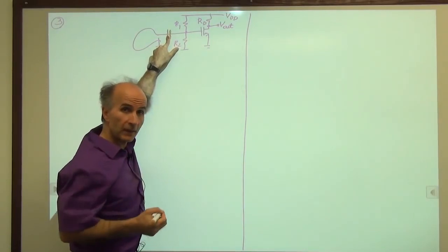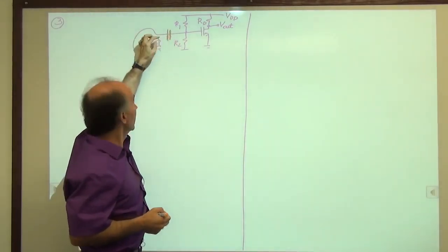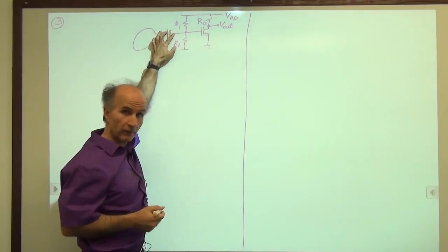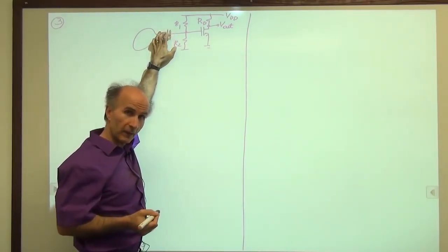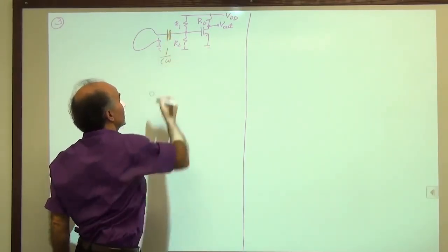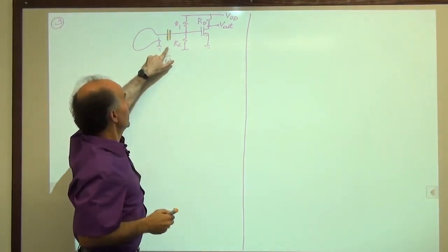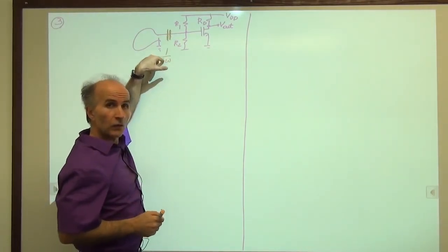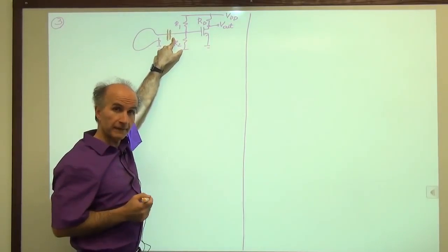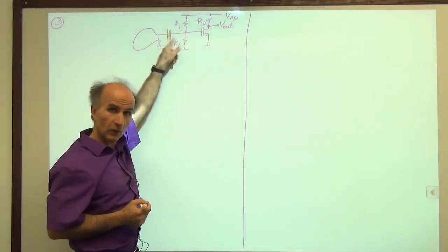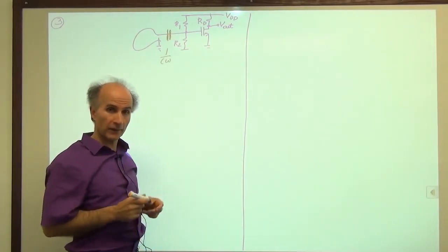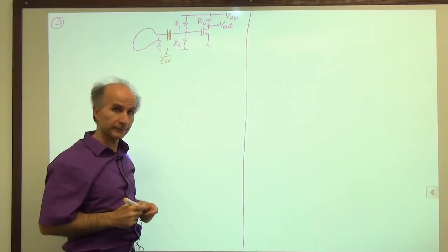And when the signal comes in, this antenna produces a signal at this point. That signal can go through this capacitor if the capacitor value is large enough. If you remember, the impedance of a capacitor is given by 1 over C omega. So if C is large enough, this impedance is small. So the capacitor looks like a short circuit for signal frequencies. So signal goes through, the DC doesn't go either way, we're good. So that's a quick fix of this type of situation.